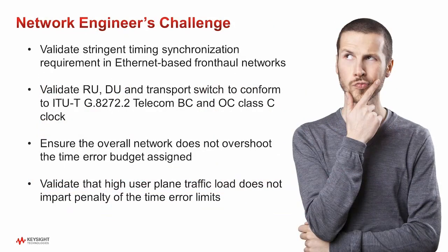So validation and benchmarking of the synchronization plane is an absolute must to ensure the network does not exceed the time error budget, and the different 1588 profiles need to be also tested for conformance. And also at a network level, the engineers need to ensure that the synchronization plane is not disturbed by anything else. For example, it's not disturbed by unexpected bursty traffic or high user plane traffic scale.